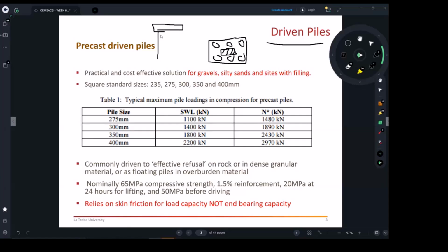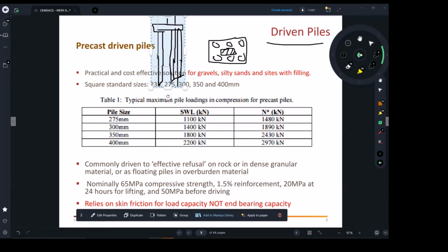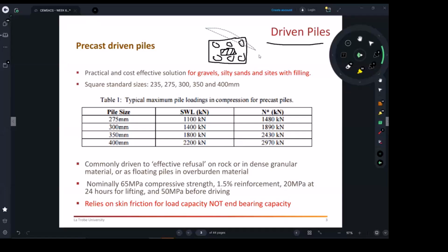The pile cap is sitting on the driven piles, which can go 20-30 meters into the ground, and on top of the pile cap, you will have what? That big column which goes up, because basically the soil is very weak in that area, and again we're carrying a long tower there, so the loads are really strong or very high.